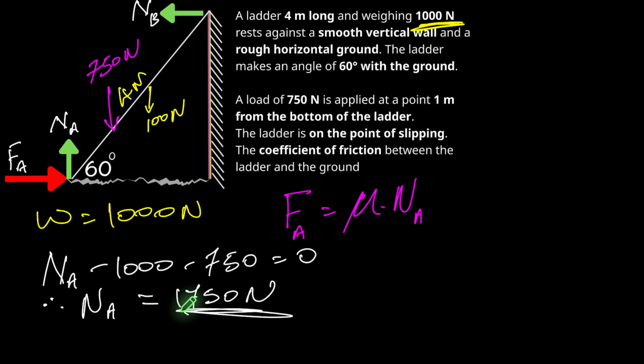So I'm going to set out another set of equations now where the total horizontal forces should be equal to 0. Here we have only two horizontal forces: we have NB and we have FA. If one direction were to be positive, the other were to be negative, let's say we would have NB take FA should be equal to 0, or the other way around is fine.